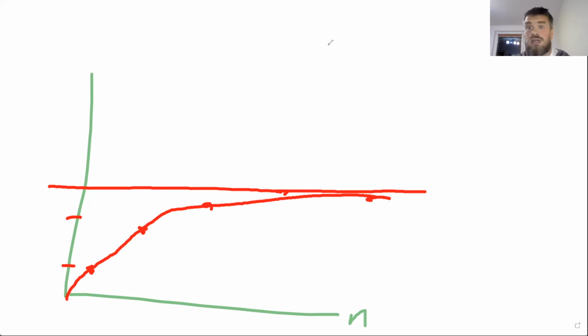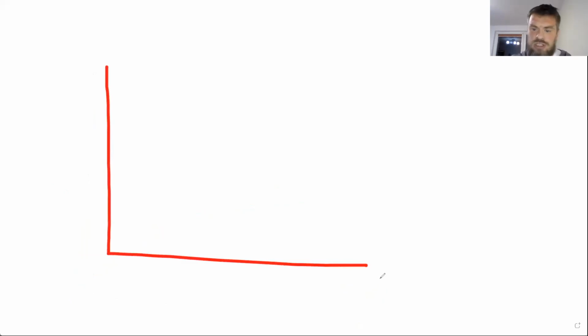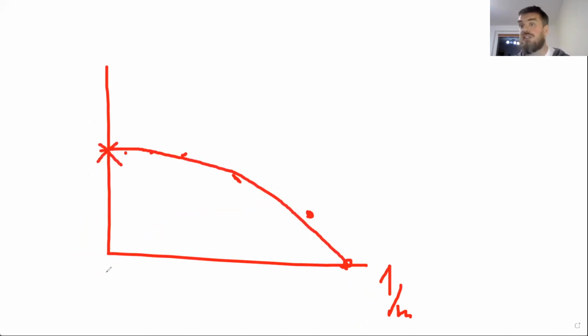I wasn't sure because it's similar to Poisson. So the trick here to make it easier on you would be to, instead of using n, use 1 over n, because then you have a chart where this is few elements, this is more elements, because I'm dividing more. And it's actually easier to say when you are crossing 0, which would be the infinite amount of elements, and that would be the correct answer. Although, do you really want to execute your nonlinear FEA analysis 24 times to get it? That's tricky. It comes with experience, I guess.